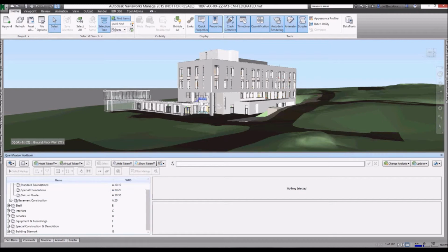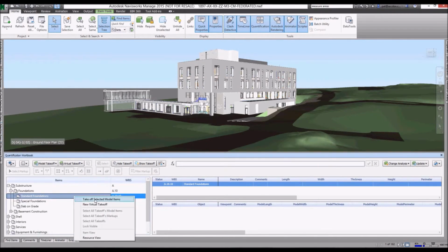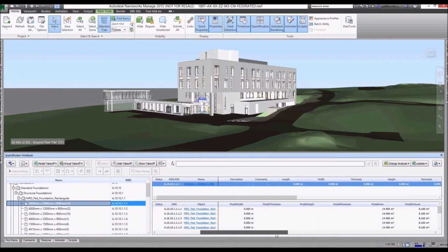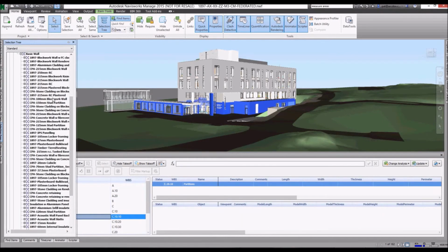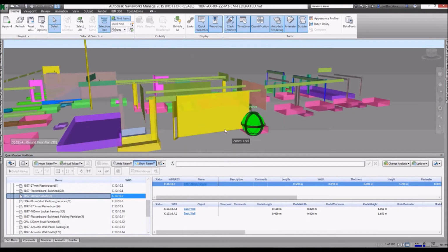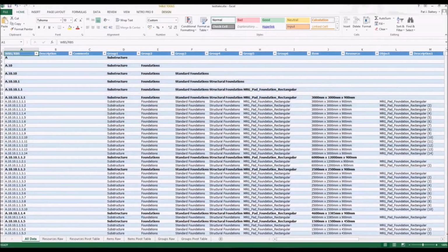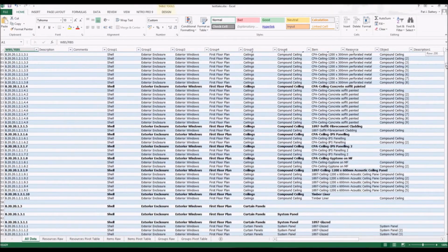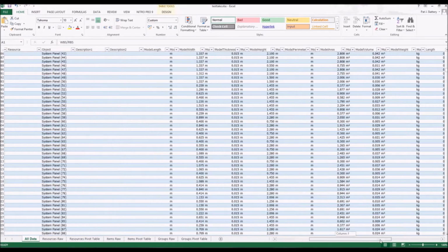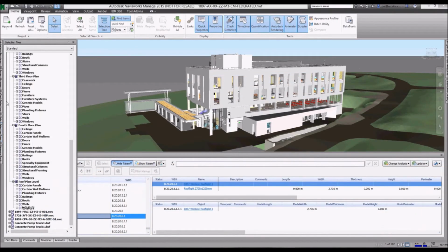Navisworks also includes quantification tools that allow you to create catalog recipes for taking off elements in the model, either 3D model takeoff or 2D takeoff from drawing sheets. 3D takeoff allows elements to be highlighted in the model and attached to items in the workbook. Items which have been taken off can be isolated or hidden in any view. You continue to highlight and take off the model elements, and should the model be updated at any stage, the Change Analysis tool will identify and highlight the differences. The takeoff can be exported to Excel if required, and possibly linked to other quantification and bill creating tools.